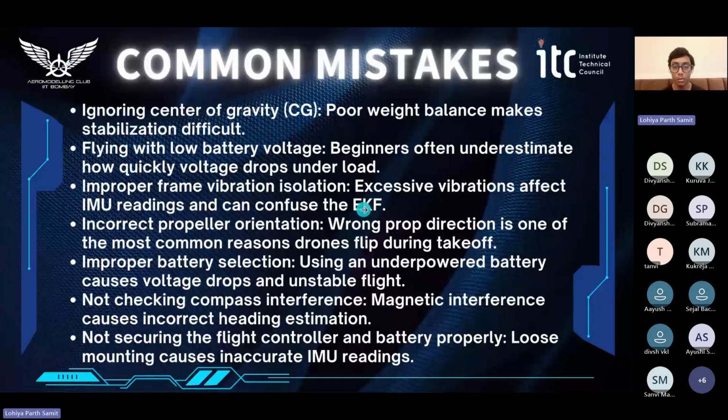Then we have the incorrect propeller orientation. That is, if we, for example, install a clockwise rotating propeller on an anti-clockwise rotating motor. So that would not give us any sort of lift. It would in fact take our drone down. So the wrong prop direction is one of the most common reasons drones flip during our takeoff.